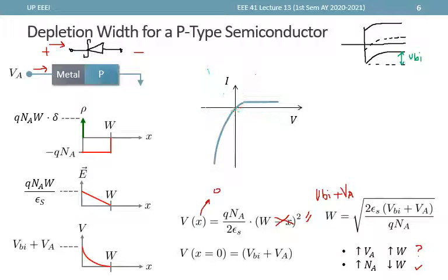And so this IV curve is actually a result of the notation of the voltage and the current. However, we'll still use that the semiconductor is grounded to be consistent with our assumption that the voltage is 0 at the flat band region of the semiconductor.